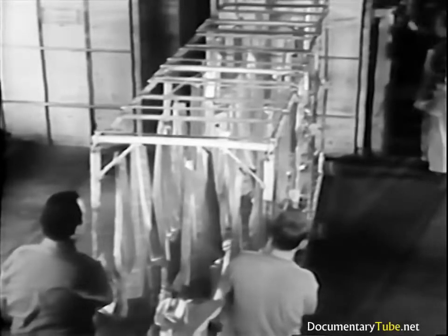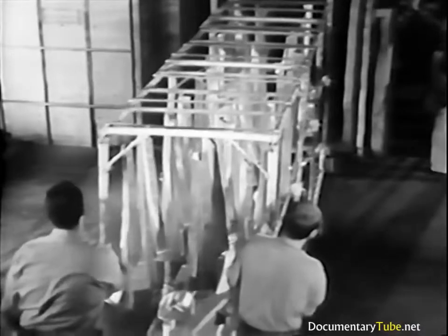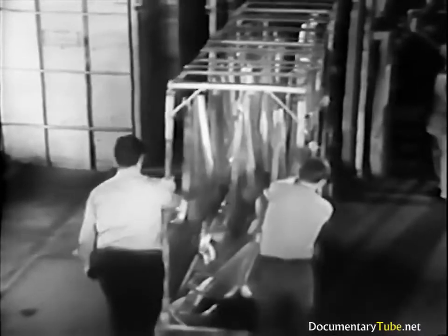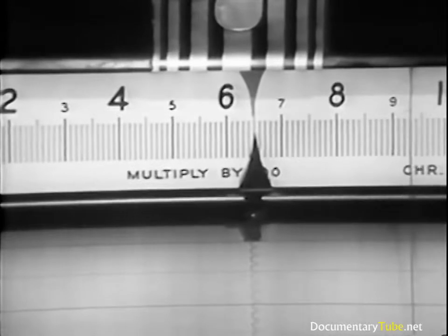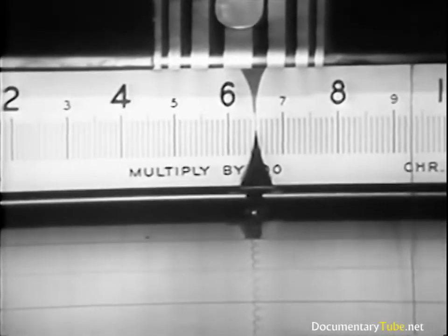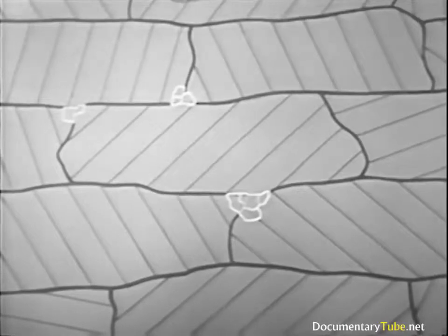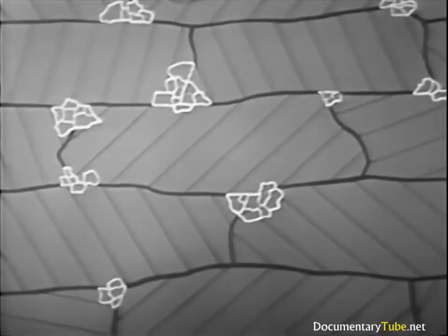In order to remove the effects of cold working and to soften the alloy for further forming operations, the strain-hardened alloy is annealed in an air furnace. Annealing is done at approximately 650 degrees Fahrenheit, and its effects are almost instantaneous. Annealing first relieves the internal stresses caused by cold working.